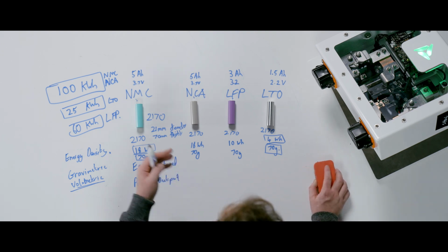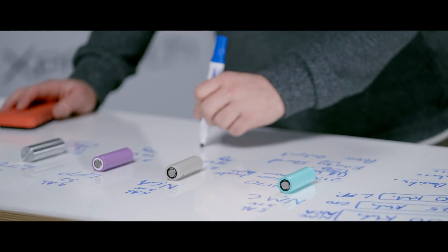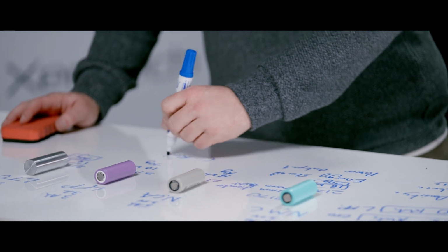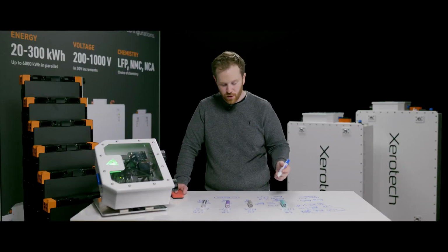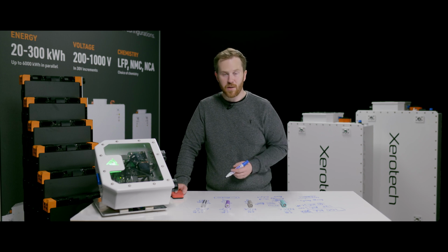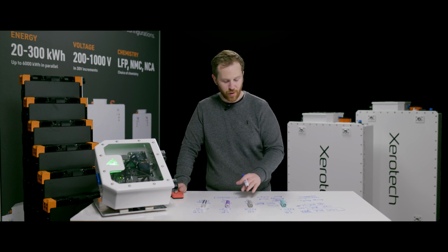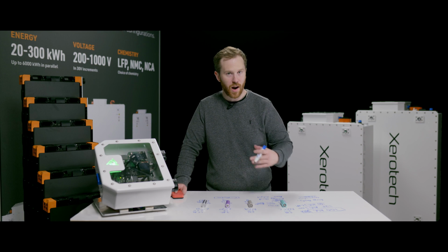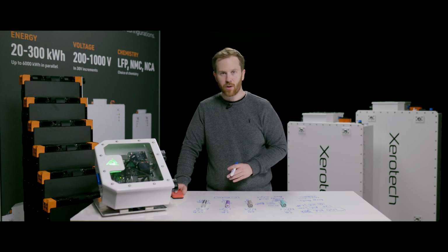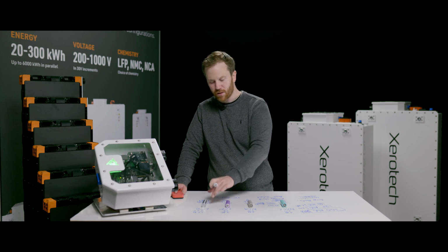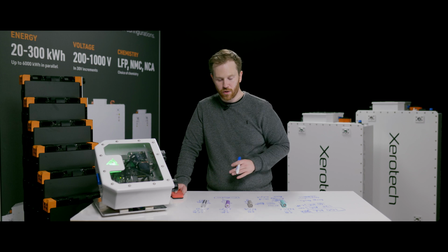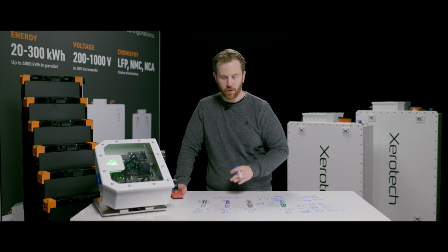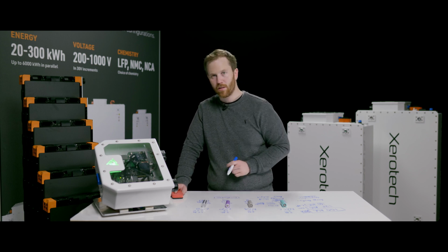You'll have recalled in an earlier video we talked about C rates. NMC chemistries and NCA chemistries can only really do a couple of C typically. Power cells, a specific variant of these, can do higher C rates, but LTO can do 10C, 20C, 50C because it's so robust and stable. LFP is somewhere between the two, but it's much closer to NMC and NCA compared to LTO.